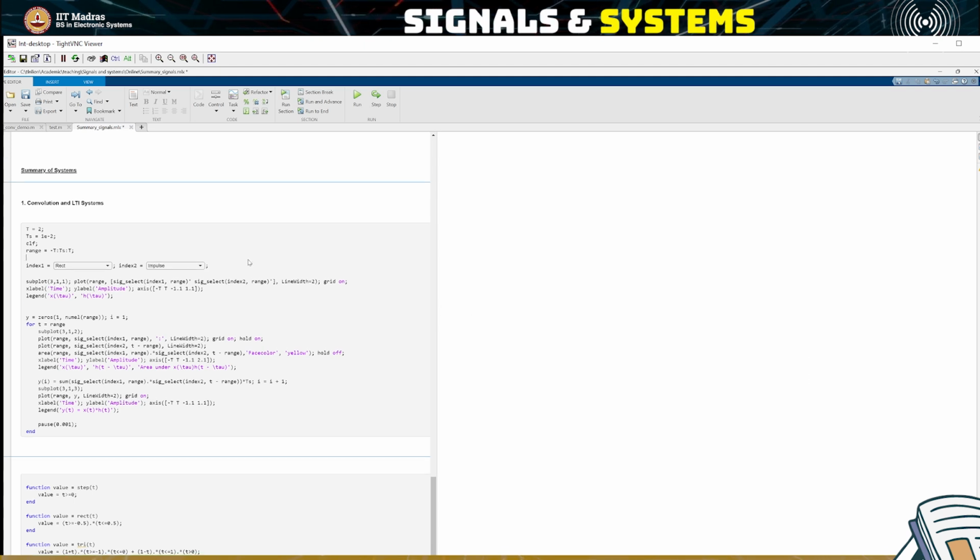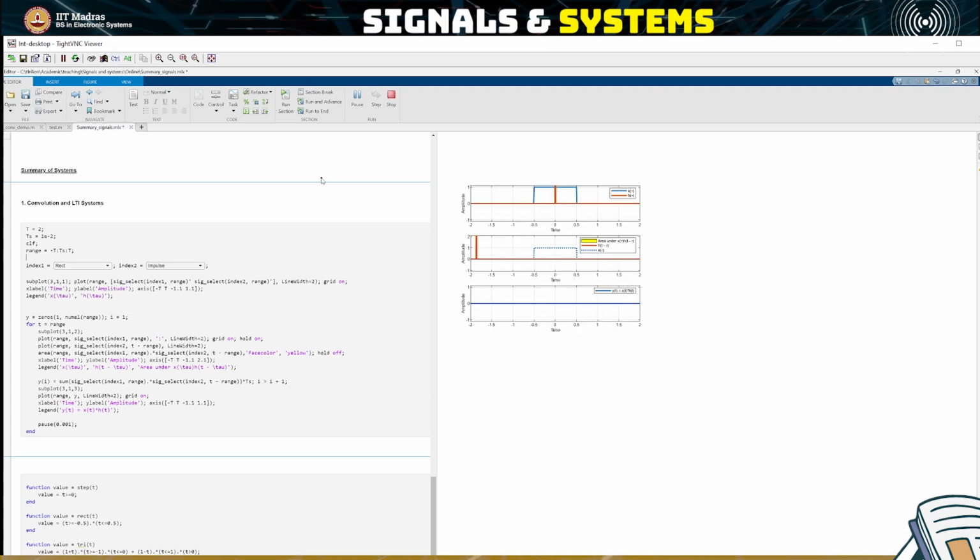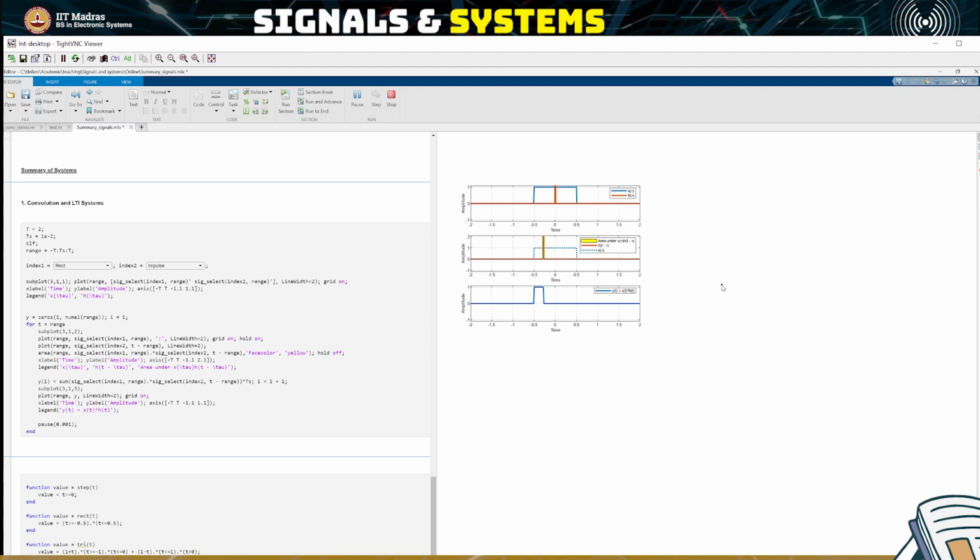Let's see what happens when we convolve the rectangular signal with the impulse signal. As you can see here, the impulse is time reversed, which is exactly the same because it's an even signal, and it is moved from left to right. So it's 0 till there is an intersection, and when there is an intersection, remember, all you're going to do is just sample each and every point.